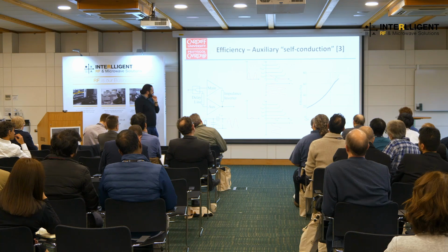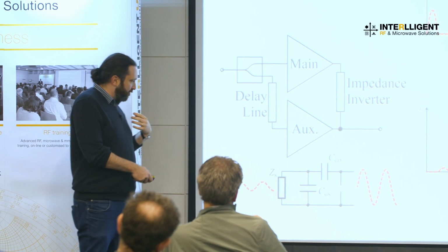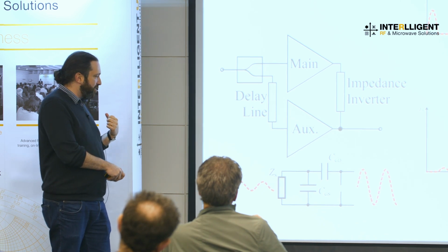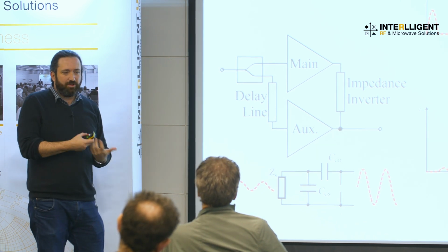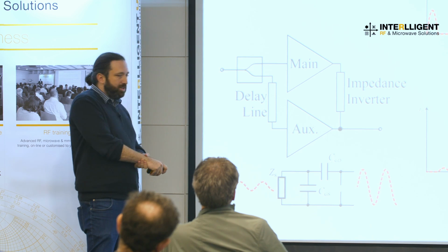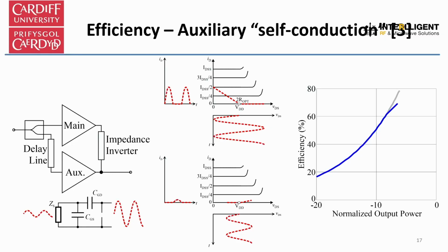And then there is another aspect, which is always affecting the gamma out if you want, but it's more related to the feedback of the device, which again might have a higher impact at higher frequency. So when your transistor is off, you don't have a current source here, but you still have the capacitance. So you have a feedback capacitance and you have the input capacitance more or less in parallel with whatever impedance you set as the source impedance of the transistor. And this is a voltage divider. Well, how much is that voltage divider? It all depends on how ZS is.